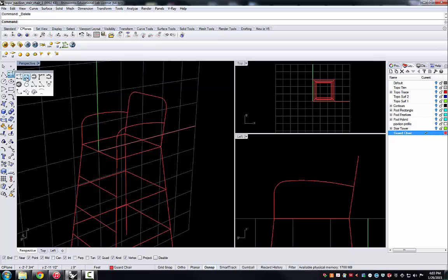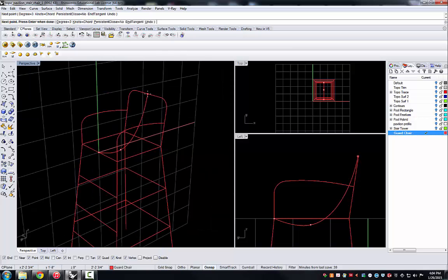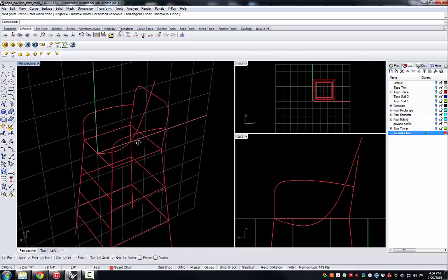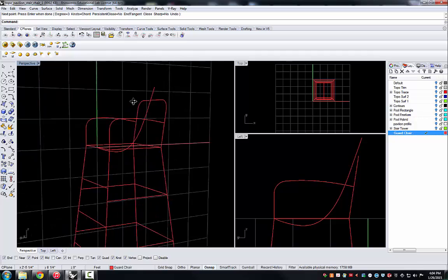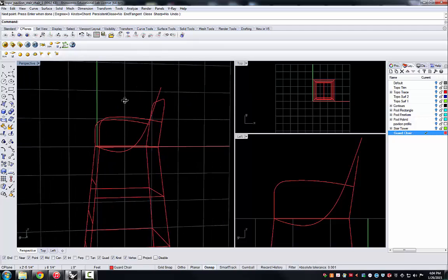that interpolates points, and I'm going to start from the midpoint of that front edge of the chair. I'm then going to come in the perspective view down somewhere where the seat can go depress a bit below. I'm then going to come up somewhere near the midpoint of the back of the chair, and then I'm going to finish above the back of the chair. So I've got a pretty simple curve that is on this new construction plane, and that I made by clicking on some geometry, but clearly not clicking on other parts of the geometry in order to make that.